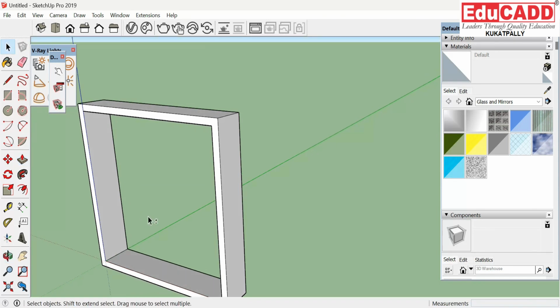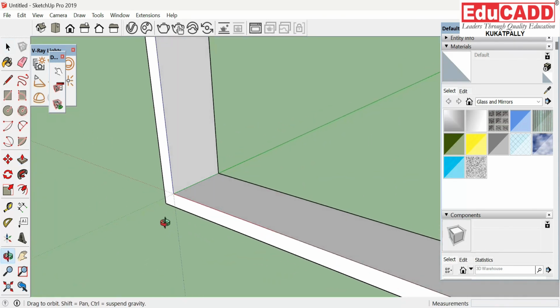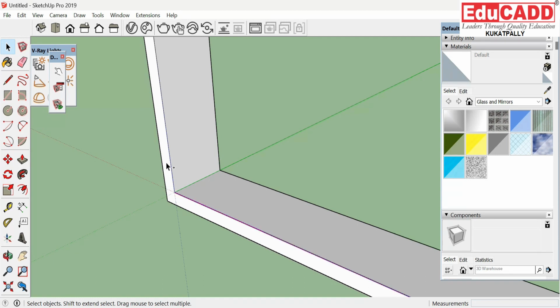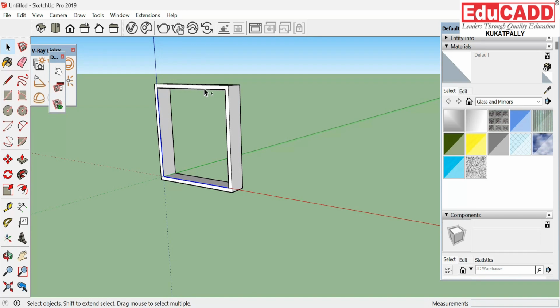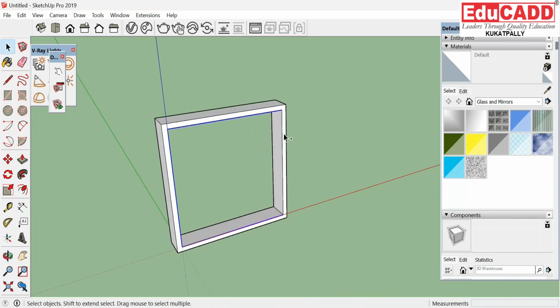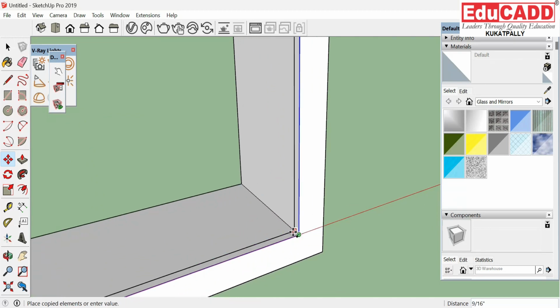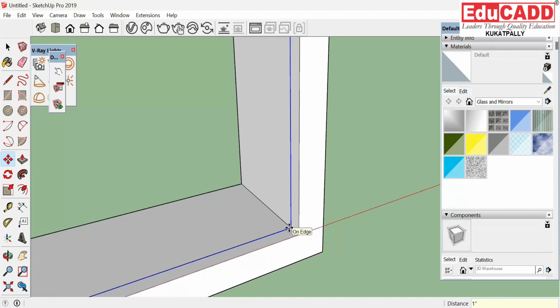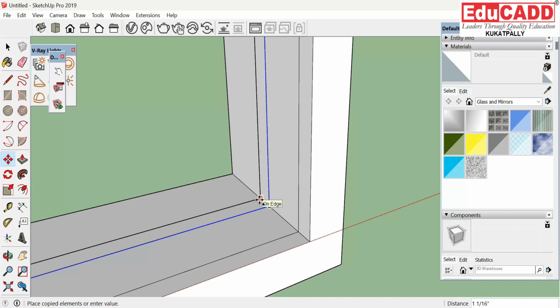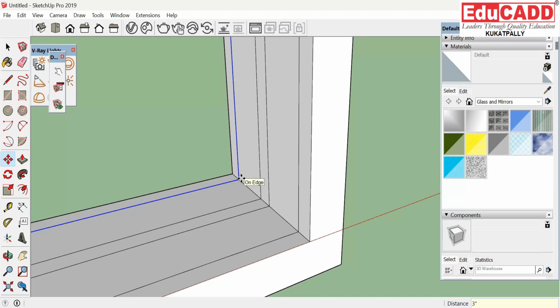Right. Now we are going to create the guides. I'm selecting the inner edges. I've selected the inner edges using the move command. I'm clicking on Control. Now I'm specifying 1 inch, taking the 3 inches as the sliding movement, and now going for the 1 inch and another for the 3 inches for the sliding movement.